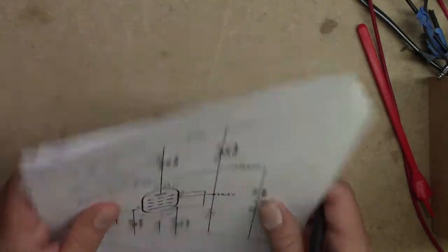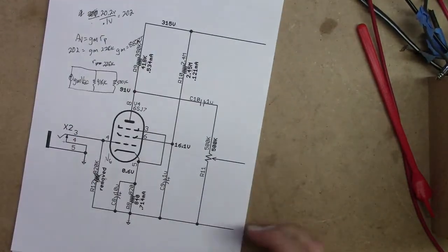Okay, let's hop back to my desk and wrap this up. If you made it this far, I hope you learned a little bit about the flexibility of using pentodes for preamps and the selection of the screen voltage and how it impacts G sub M. That enables you to control the plate impedance of that particular preamp, and from that, you can tailor the sound in different ways.